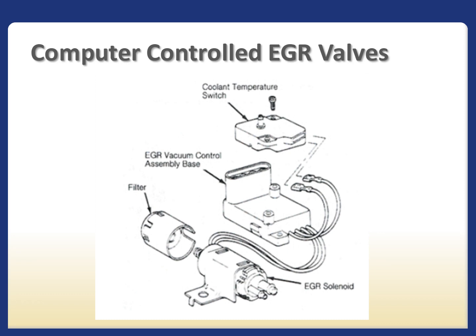A computer-controlled EGR system lets the computer adjust the EGR system operation. The computer adjusts the EGR operation based on signals from various switches and input from the coolant temperature, throttle position, mass airflow sensor, manifold absolute pressure sensor, park neutral switch, and other devices. Pulse width modulated EGR valves use short electrical pulses sent by the ECM to the control assembly solenoid to regulate EGR function.